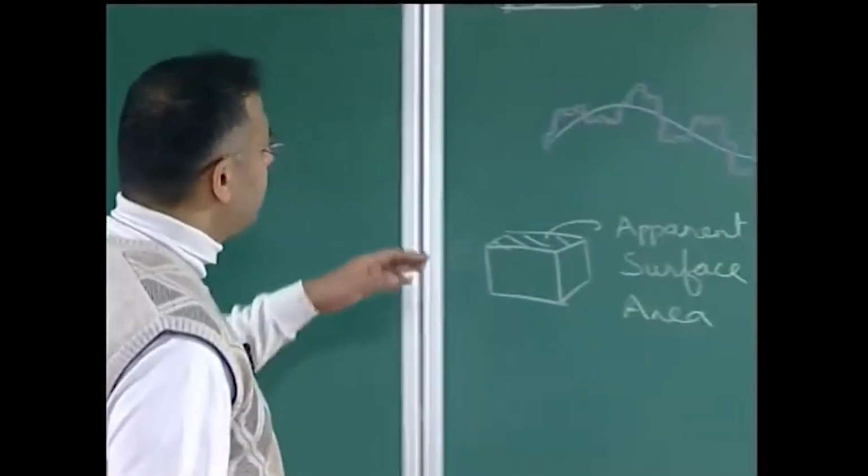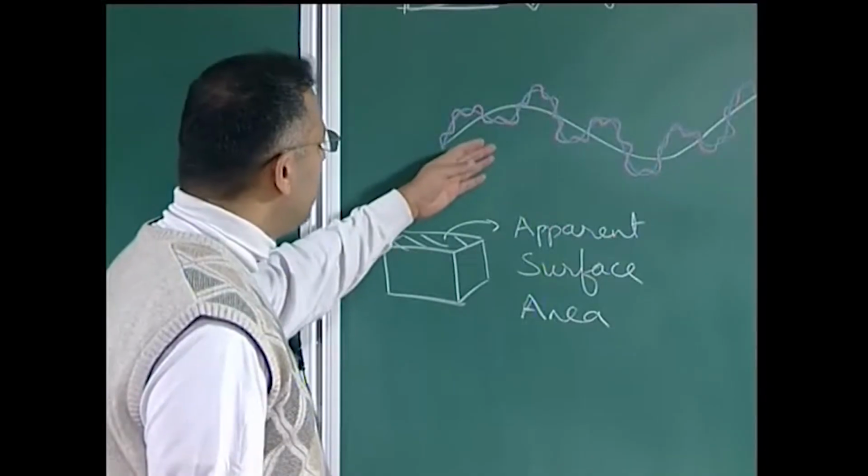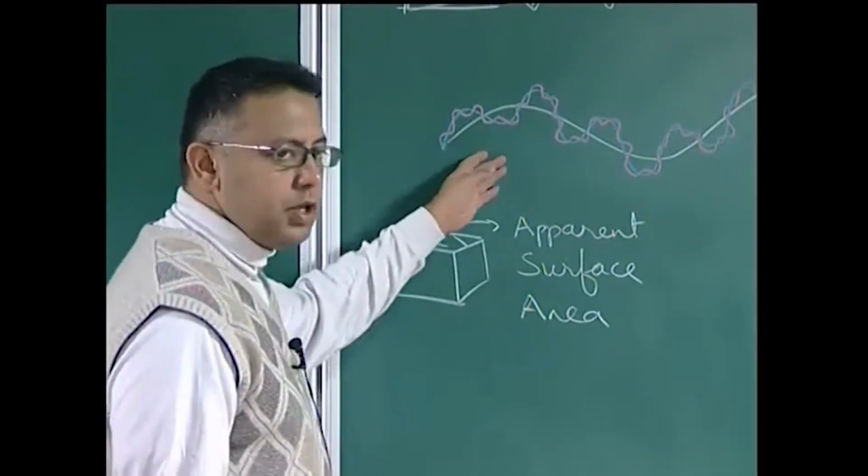So, this kind of construction you can visualize as some kind of an analog of the surface roughness which we had considered. Of course, this is not a very simplistic kind of surface roughness like the schematic analog which I showed you here. This consists of a very specific kind of structure, and this structure, as you might imagine, has to perform other roles apart from being superhydrophobic, because a leaf is a living entity, and the leaf surface has to perform other roles like photosynthesis etc. And this structure which is making it superhydrophobic cannot interfere with other roles of the leaf, and this is what this beautiful hierarchical structure consisting of micro protrusions and nano hairs does.